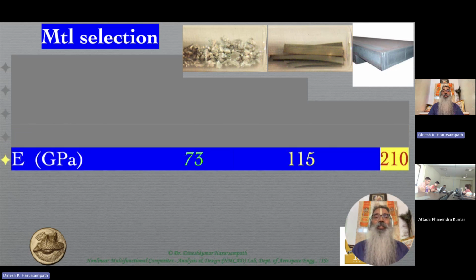Okay, so let's check out the Young's modulus. Remember that we're dealing with metallic alloys here. Whether metals or metallic alloys, they're typically isotropic, in which case, whether it's the tensile strength or the Young's modulus, I don't need to specify in which direction the property is, because it's the same in all directions for that given alloy. Once the alloy is specifically chosen, that's what it is.